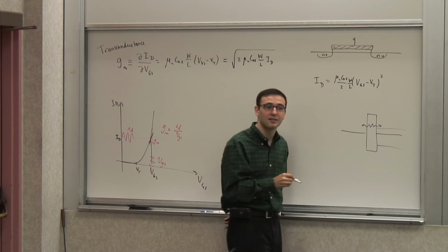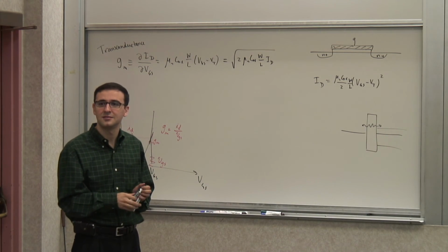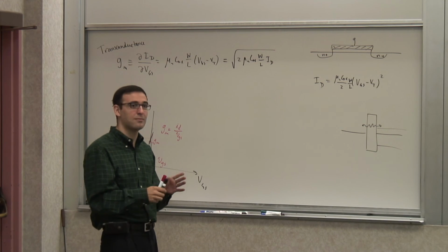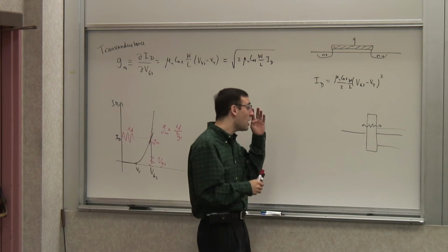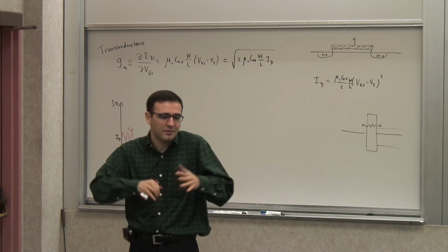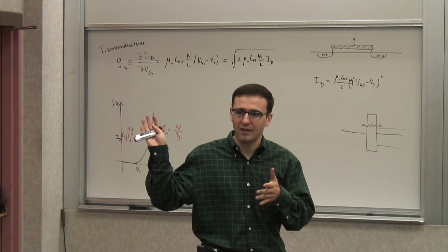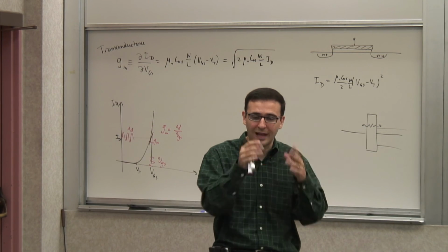Yeah, tunneling. The electrons literally tunnel through the gate. And it happens, and therefore you have the gate current. For a single transistor, it's not very large. It's in the range of hundreds of picoamps, and it depends, of course, on the gate offset and a lot of other parameters, so it can vary a great deal. It's picoamps, nanoamps kind of things.